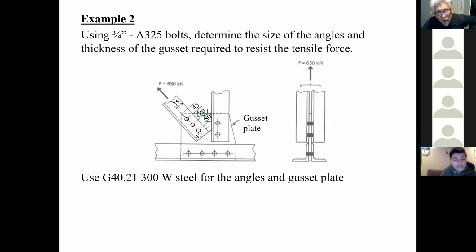Therefore, by putting 80, I respect that. I know the edge distance is the same, so I just make sure my geometry works out nicely. This is what I came up with in terms of spacing my bolts, and I know these spacings will respect the values in table 6, so I will not sweat over that.